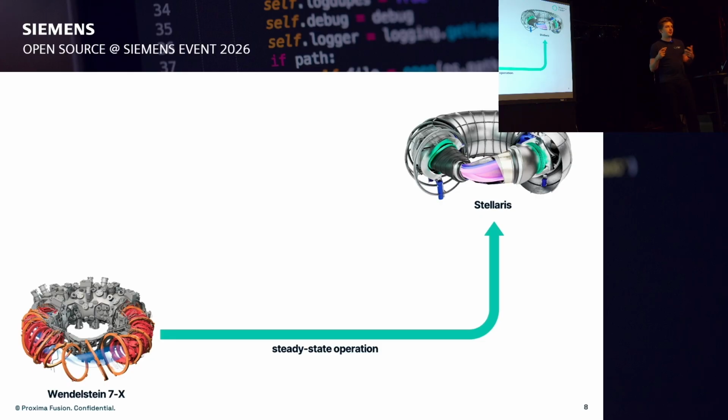And at these temperatures, if you build the coils out of certain materials, in this case it's called niobium titanium, this becomes superconducting, so you don't have losses, electrical losses, when you generate these big magnetic fields, which is a game changer for creating these strong magnetic fields that we need to contain this hot fusion plasma.